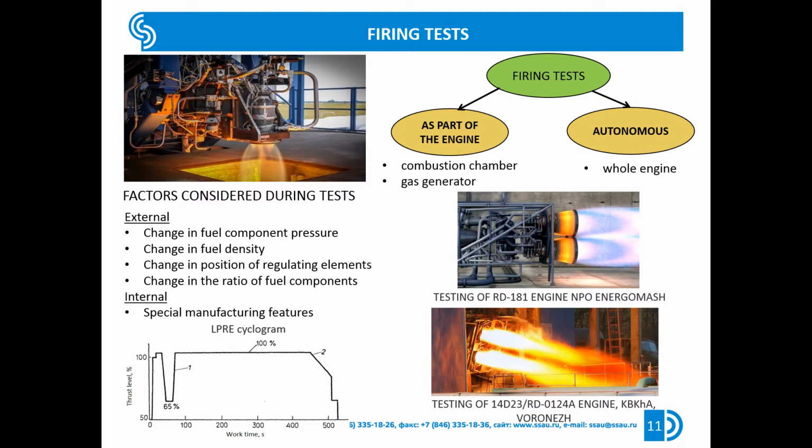Engine operation is tested under various combinations of external and internal factors during the firing test. External factors are defined as physical effects on the operating mode of the LPRE caused by external conditions. These include changes in pressure of fuel components before the pumps, changes in the fuel density due to the changes in fuel temperature grade, changes in the position of thrust regulators and fuel component ratios caused under operating conditions by controlling actions from the rocket or spacecraft control system.